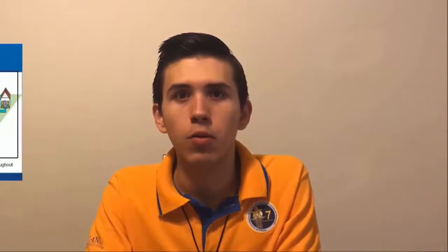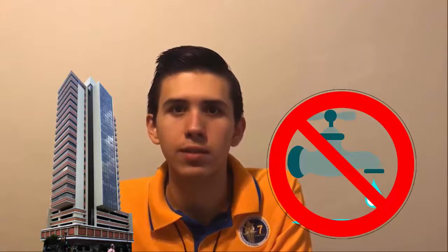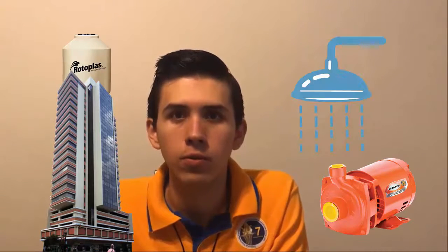The first point to be discussed about the stage 1 of fluids are the water distribution networks at homes. Water that arrives to our homes is stored on high towers or tanks at the cities. This is done with the intention that the water arrives to our homes with enough pressure. When on a high building water is still not having enough pressure to reach a certain height, the solution is to put a tank at the roof of the building and carry up the liquid with water pumps. This way, the water can reach the homes by fall.